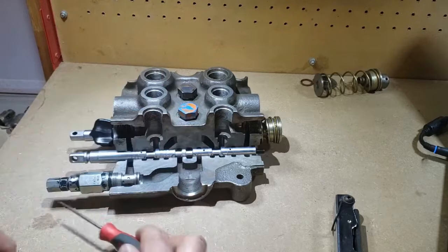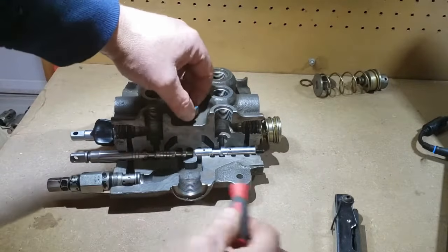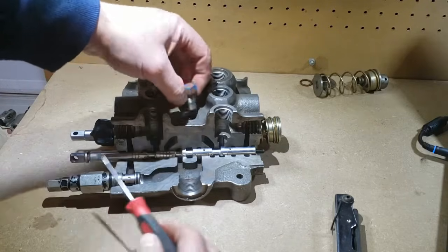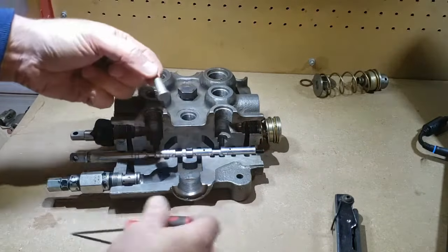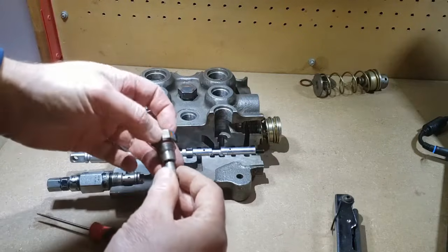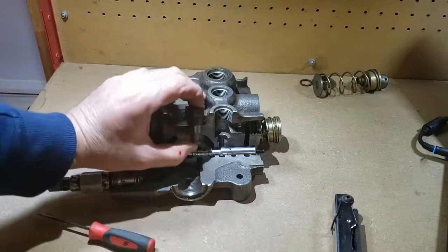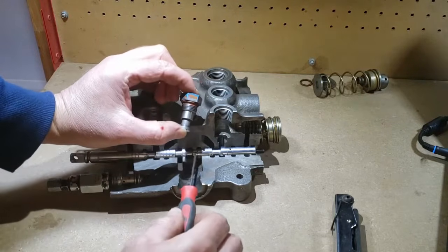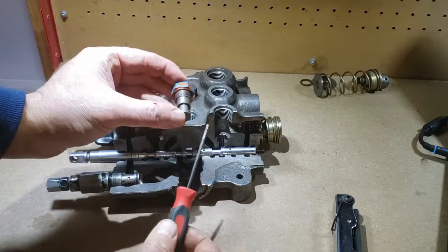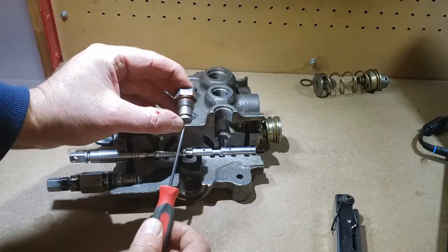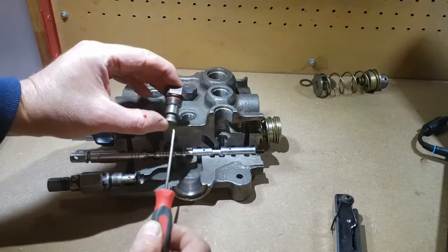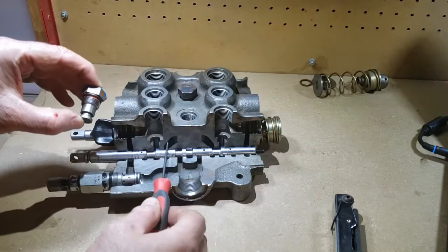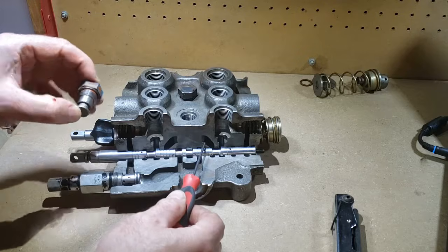Now I don't see the load check valve here because the way this has been machined open, the load check is actually gone. So I'm going to steal the load check out of the tilt function, and we'll kind of position it where it would sit in the lift function, kind of here. And what's going to happen when the oil is blocked by those 2 lands for the open center flow path is it's going to be able to then push open this load check valve. Oil can flow past this poppet of the load check valve into this bridge passage or parallel feeder passage.